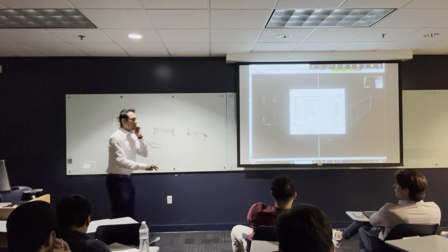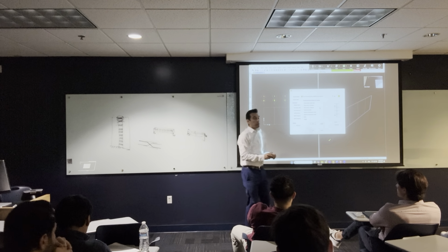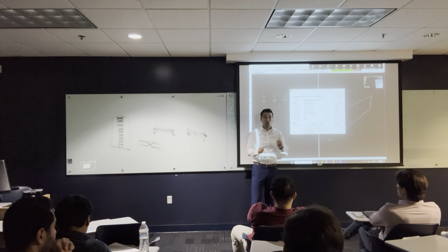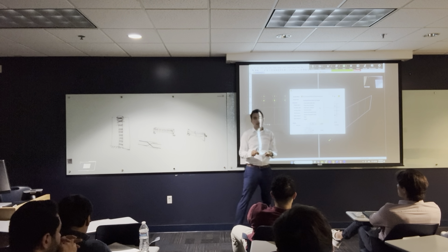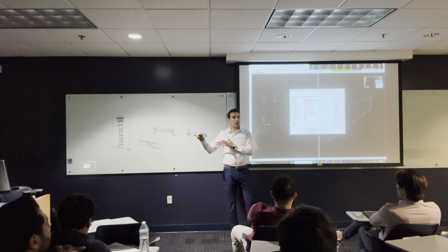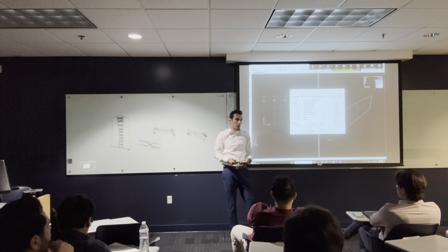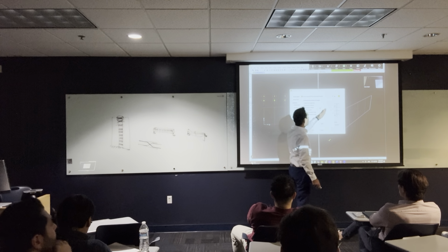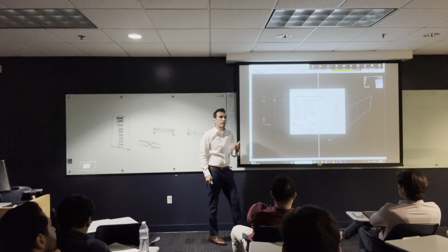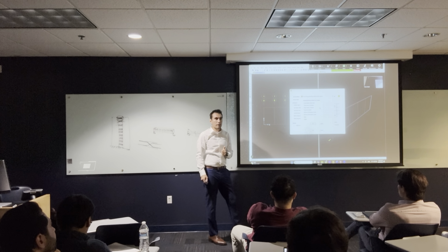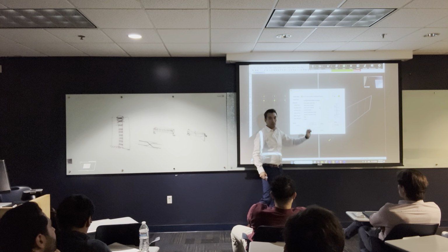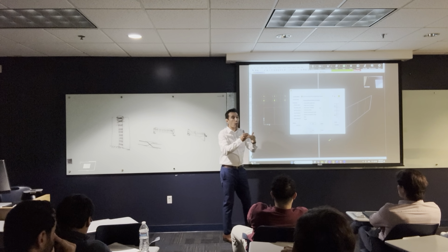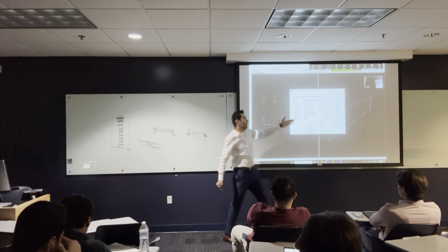Basically, sometimes when we design for seismic, the seismic design assumes that the cross sections are already cracked to do seismic analysis, because we do something, we were going to talk about this concept. We reduce the stiffness of the whole structure. So when we reduce the stiffness of the whole structure, we make the stiffness modifiers for the structural elements a little bit less. Like the columns, we reduce them by 30%, so we take a factor of 0.7 on the stiffness. The beams, we make them 0.25. The slabs, make them 0.5. So when we reduce the stiffness of the structures, we use these modifiers.